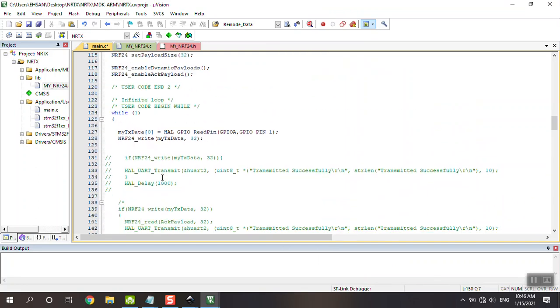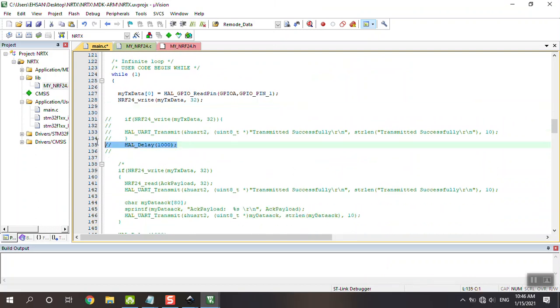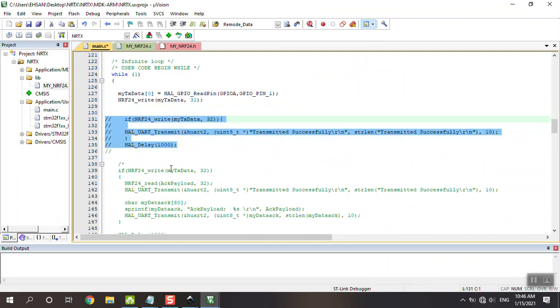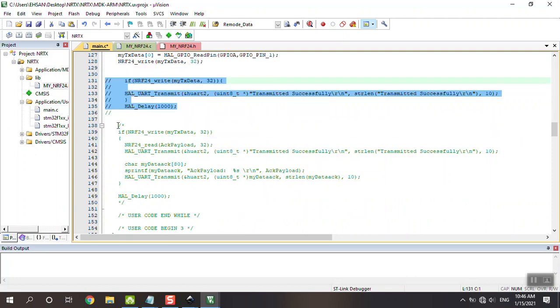Add this file. Okay, I write three forms for transmitting. This first part is for pressing the push button on PA1, and we must turn the LED on the next board, I mean the receiver. The next part is for transmitting data or a string to the receiver, and the last part we transmit the data with